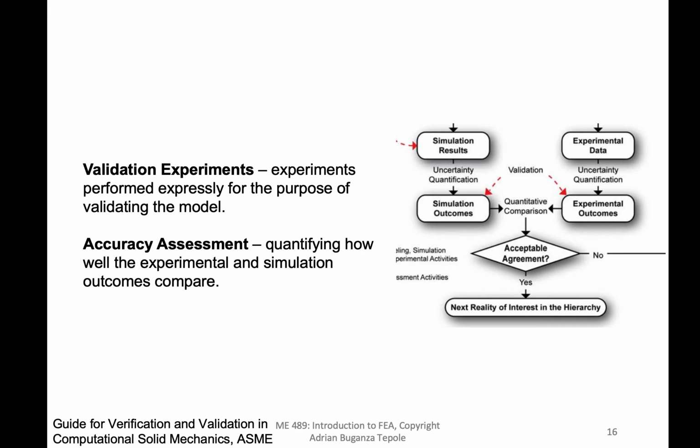In terms of the validation, as I said before, the validation is to check whether or not your computational model describes the physical reality. So for that, you actually have to do experiments. You don't want to do experiments that are way too expensive. You don't want to do experiments for every single simulation that you do. So you can imagine if you are designing a part, and you have some finite element model for that part, and you want to validate that that model represents the reality, the stress and strain distribution that that part will undergo in the setting where it will operate.